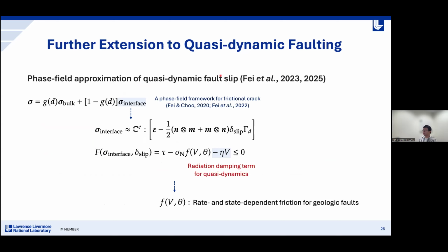We thought this model can also be pretty valuable for modeling some very important shear fracture problems like the slip and growth of faults. So we further extend the model by incorporating the rate and state dependent friction for geological faults. And also we make use of this quasi-dynamic approach to capture the fault rupture for computational efficiency.